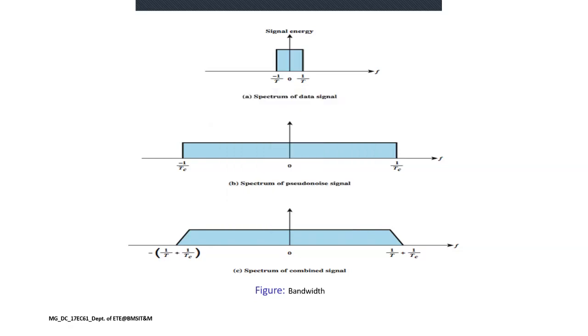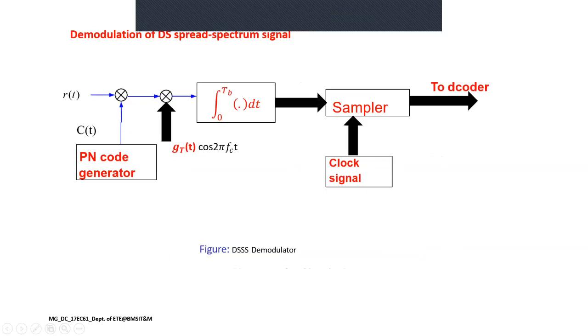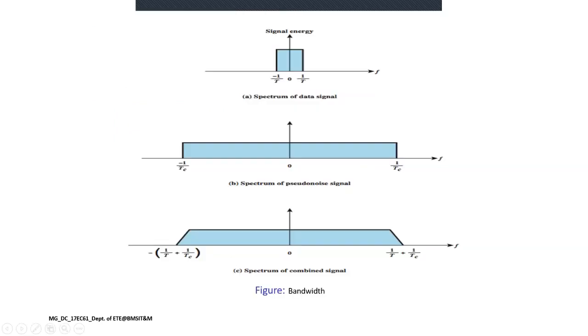So this is basically the message. Sorry, this is the pulse of the message signal, and the spectrum of the pseudo-noise signal. The convolution of these two, that is in frequency domain. I said in time domain it will be multiplication of these two. If I multiply these two, means two rectangular pulses of different width, I will be getting a trapezoidal wave. This is what the spectrum of the...